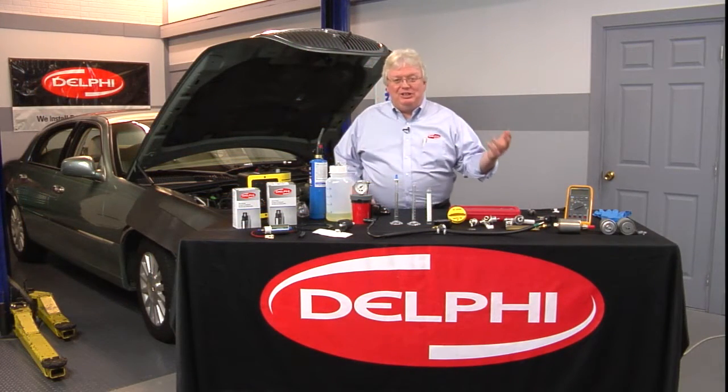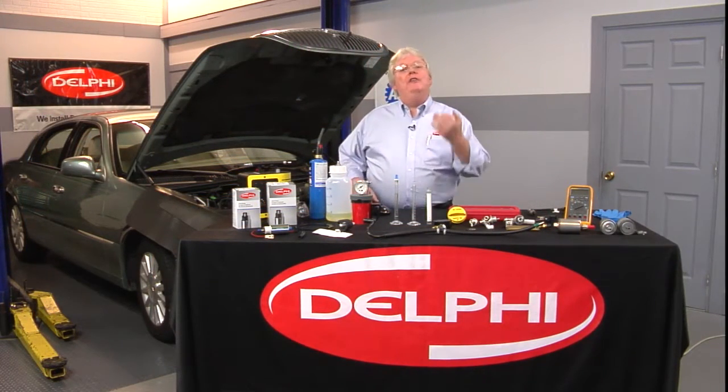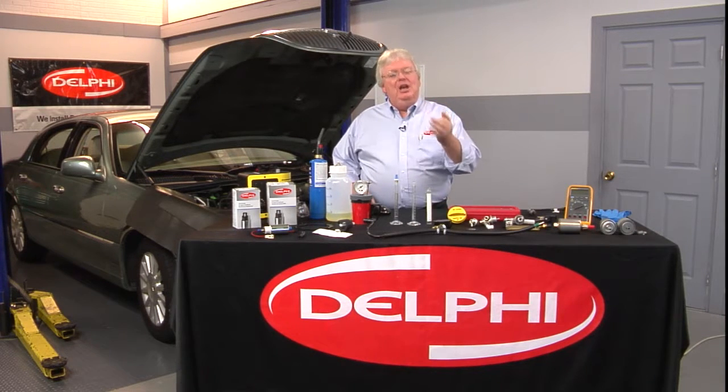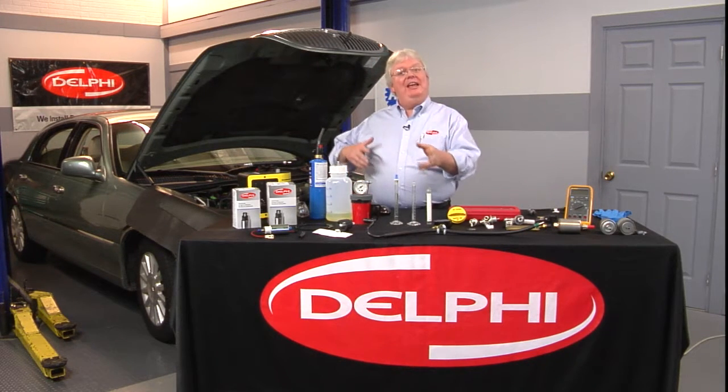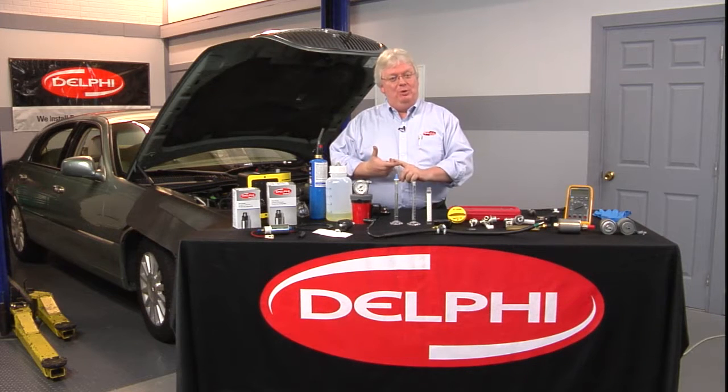Well, that last question we had about the effect on fuel trim of a vacuum leak on a speed density vehicle was kind of answered there on that Ford Explorer, a very late model vehicle with the newer air fuel ratio type of sensor. It had a small effect, but not as drastic as one might think.